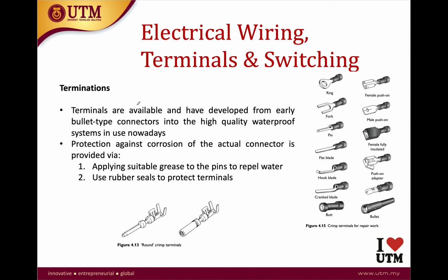Aside from that, you have terminations, or wiring terminations. Terminations have developed from early bullet type connectors into the high quality waterproof systems in use nowadays. For protection against corrosion, usually you apply grease to the pins to repel water, or you can use rubber seals to protect the terminals.